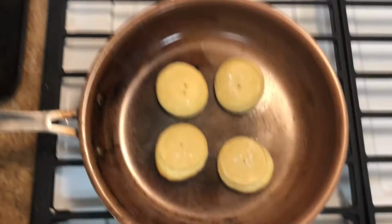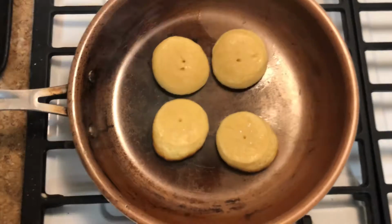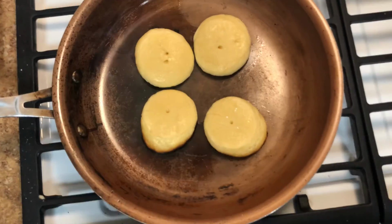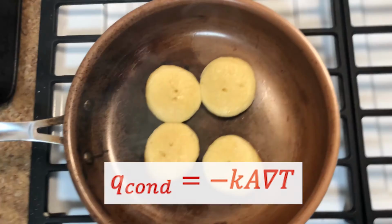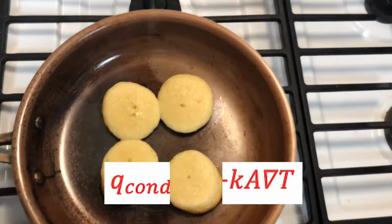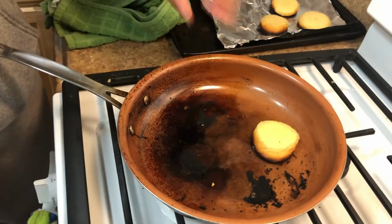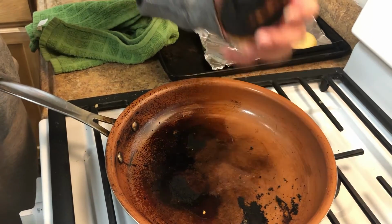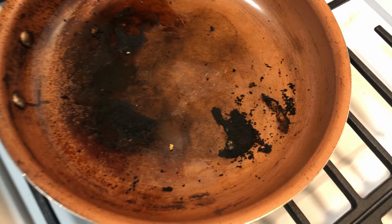We use calipers to measure the cookie thickness and a thermometer to measure the temperatures at the cookie surface and bottom. These measurements will give us dT/dx, which we can use in Fourier's law of conduction, along with the surface area of the cookie and a researched cookie thermal conductivity to find the heat flow through the cookie as it cooks. As you can see, the stovetop cookies did not turn out that great.